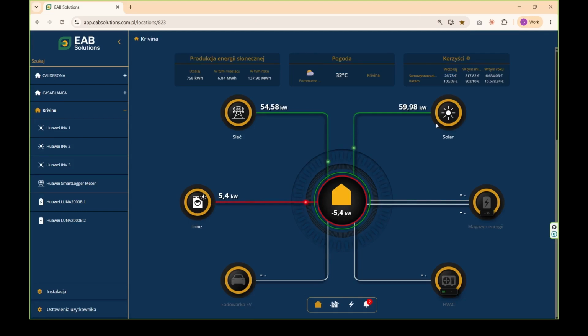We've been talking about cases where we feed electricity into the grid, cases where we're allowed to, but it's the same principle. What we'll do is charge the battery, either with solar electricity or with grid energy when the price is low, and discharge it against the site's own consumption. If we're not allowed to export to the grid, what we do is supply the site, avoiding any draw from the grid during the expensive hours, which is exactly the same principle. We charge the battery with cheap electricity, and we stop the site from consuming expensive electricity during the expensive hours by feeding it from the battery instead.